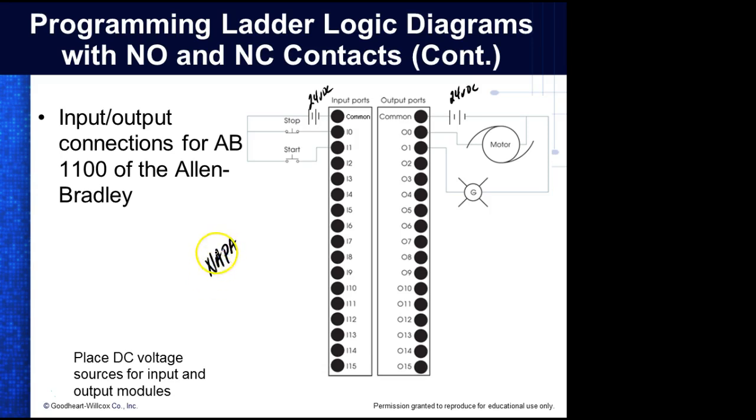National Fire Protection Association 70E. Have you heard of that? Most people call it 70E. And what did they do that hadn't been done? Well, they set up safety rules for use. NFPA 70, which is the National Electrical Code, is a code that's in there to protect equipment. It's not to protect you. Now, normally, if you install the equipment correctly, it's going to be safely installed, right? You understand? Well, they realized they did not have a standard that protected the person working on that.